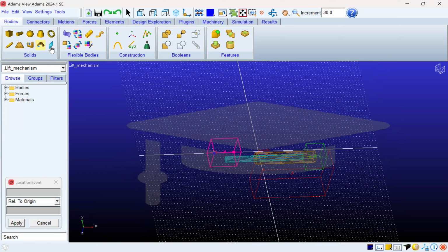So we go to the feature toolbox where we have fillet and edge, we have chamfer and edge, but we're going to use this fillet 2 to apply fillet to our mount that we created in the geometry. So I click on fillet 2.